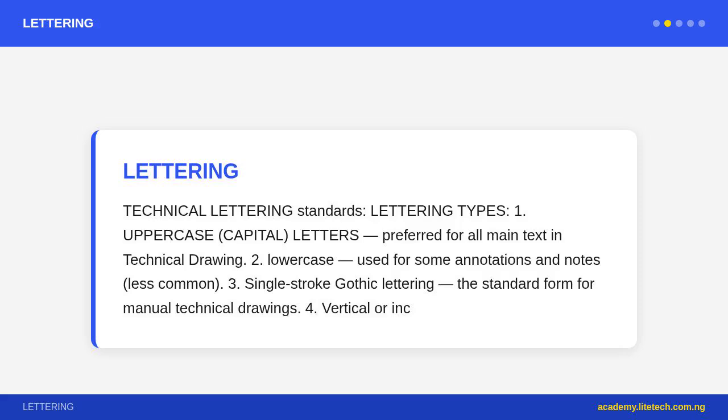Alphabet in single-stroke block lettering. Verticals, horizontals, then curves: construct letters with their most basic strokes. A: 2 diagonals plus crossbar. Careful that the peak is sharp. B: vertical plus 2 bumps. Upper bump smaller than lower. G: C plus stop at midpoint.